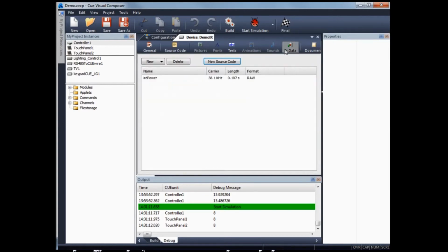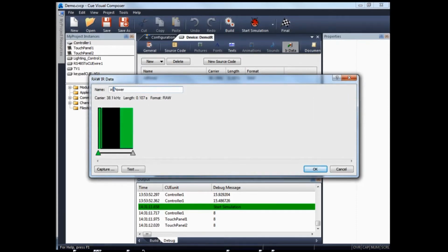Note that the infrared commands always begin with the keyword IRD. Remember to leave the tag word IRD intact. Do not attempt to remove the IRD and put in another keyword for the commands. The reason being is because this IRD keyword is reserved for all infrared commands. Once you change the IRD to something else, the source code generator might malfunction.